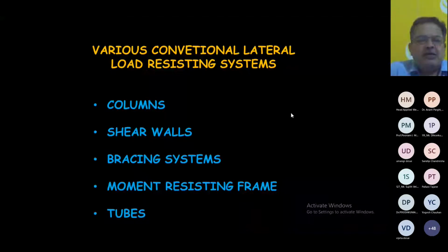But in the case of a lateral load, the action on columns, shear walls, or other vertical elements changes. Because of the lateral load, shear and moment are going to come on your vertical elements, right? These vertical elements are responsible for transferring the lateral load. So it is very important that we design these vertical elements in such a way that they are able to transfer the earthquake forces generated during the earthquake.